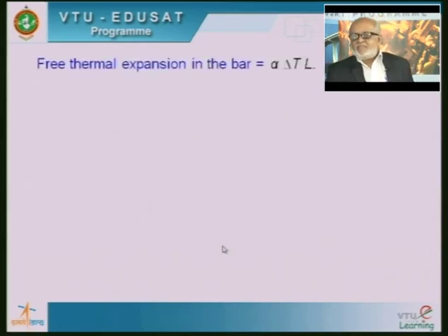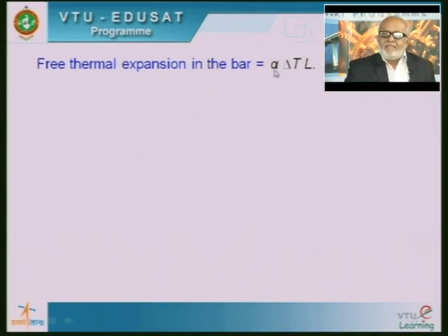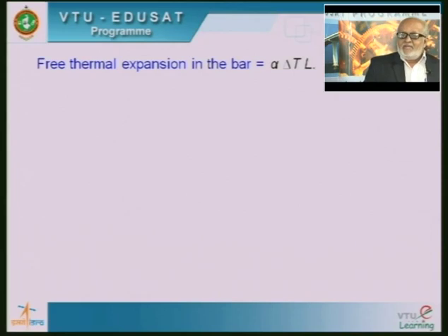What is the free expansion of the bar? The bar would like to expand by an amount equal to alpha, the linear expansion coefficient, times the temperature rise delta T, multiplied by the length L. The bar would like to expand by so much: alpha delta T L.